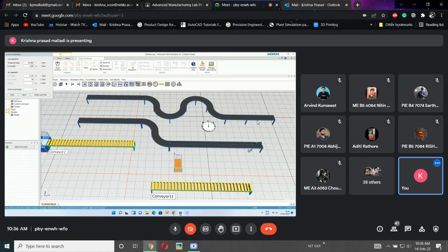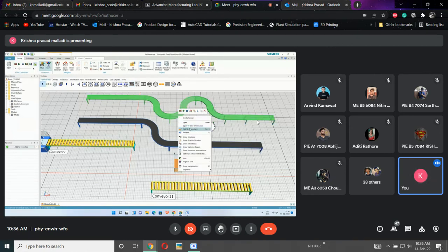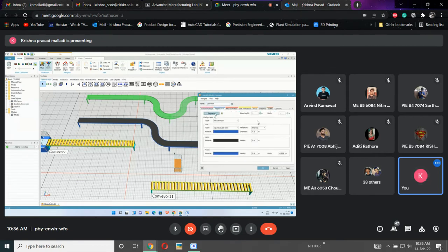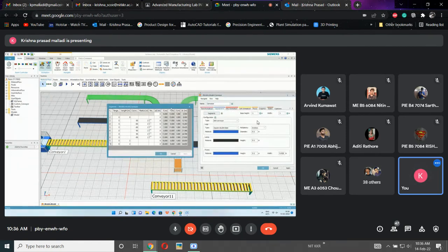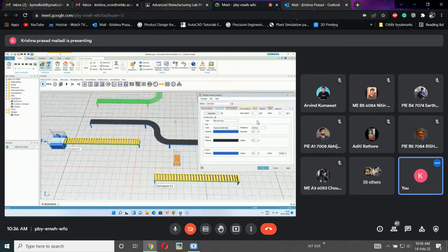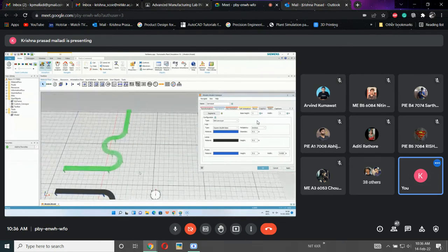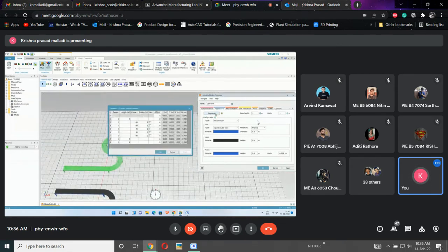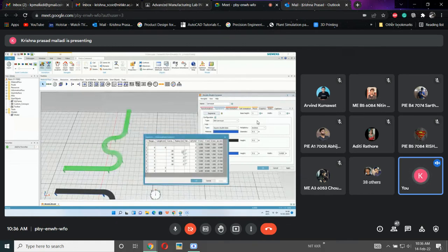Okay. Here, as said, edit 3D properties, appearance, segments. I will be entering into segments. Here there will be a lot of zeros. Here instead of 2, if I give 0, see what happened. Enter into segments. Here radius 2 we have defined. Here I am using 0 and OK.